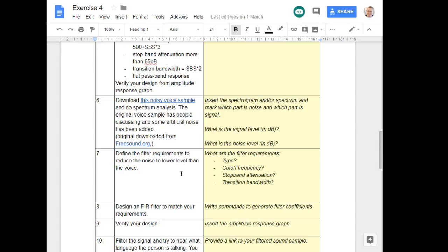It's some other language. What you need to do is to find first what is the voice and what specific properties the voice actually has, and what might be the noise. When you make a spectrum analysis for the signal, it's quite obvious which part is the noise part. And then you design a filter such that you will get rid of the noise. At least enough of reducing the noise level so that you can hear the speech. And then you start guessing what language.